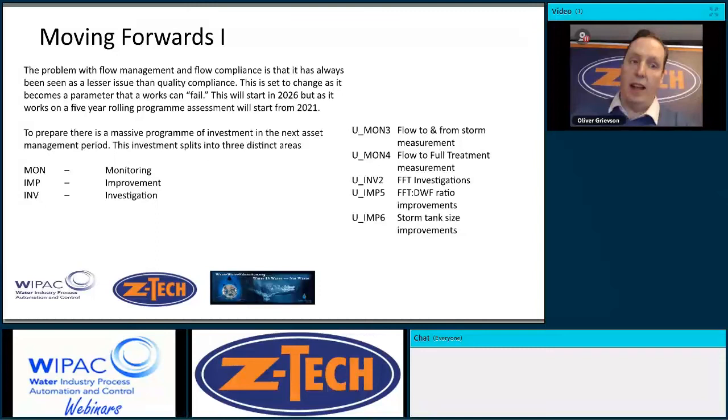The electromagnetic flow meter down the bottom, which is downstream of a balance tank, right next to a valve. The poor installation of a flow measurement device is not only going to give you bad data, but it may also give you bad control as well. There's potential for increased maintenance. We've all seen the impact of ferric sulfate dosing ahead of a flow meter